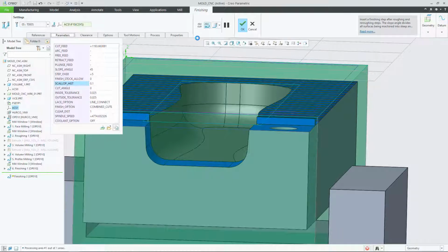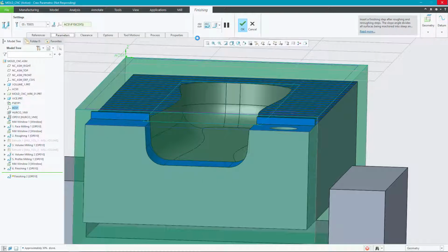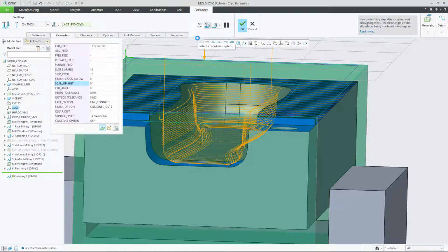So the thought is here, the rotational speed and the feed, and possibly even the tool type that you use in this original step, can be different to the speed and feed and the tool type that you use in this step here. So the first step is to do a rough material removal, and the second step here is to do a much finer kind of true finishing job, even though we are using the finishing type sequence for both of these.